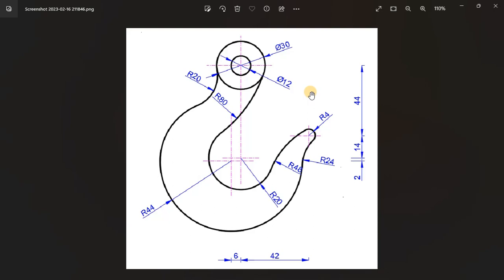We are going to use the line tool, and as we mark each point, we draw a horizontal and vertical line to make a cross, which will later turn into a center line. First, we start off randomly anywhere and mark the first point, then we go down to mark the point where we're going to project this point, which will be a distance of 44.